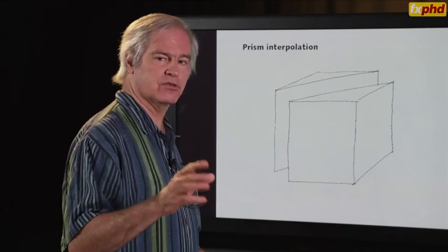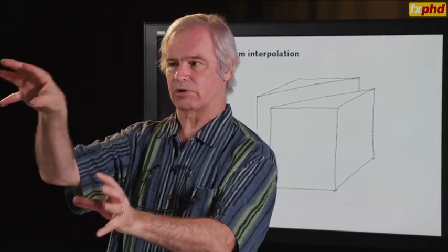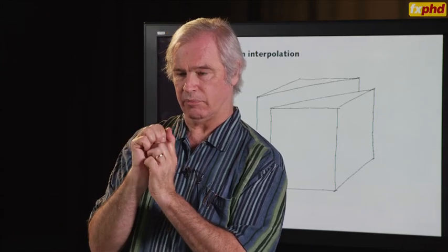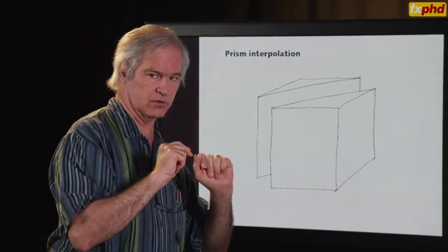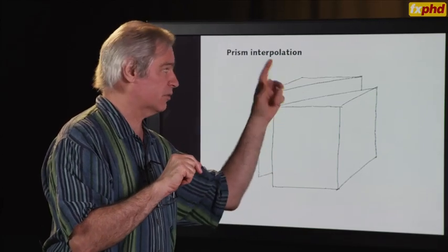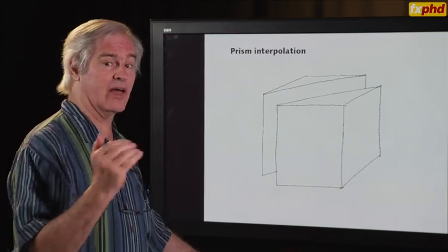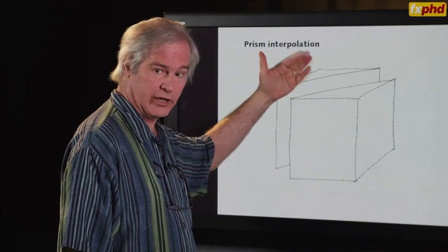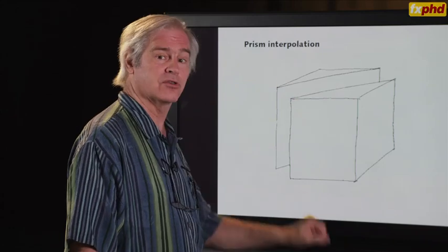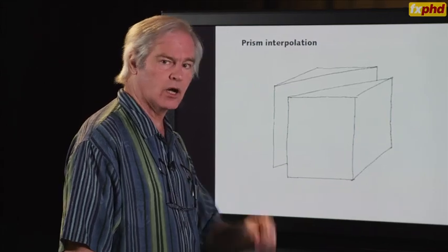And the advantage of doing so is that when we do a color lookup, instead of having to access 8 triplets from our color profile memory, from our mapping memory, we only have to access 6 triplets by simply determining which side of the major diagonal we are on. And there are people who implemented that arithmetic directly by simply comparing 2 coordinates, figuring out which prism we're in, and then accessing the 6 vertices of that prism, doing the arithmetic with 6 numbers instead of 8. But we can go one step further.